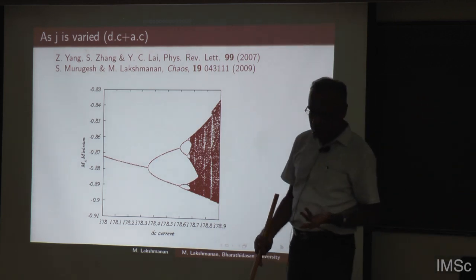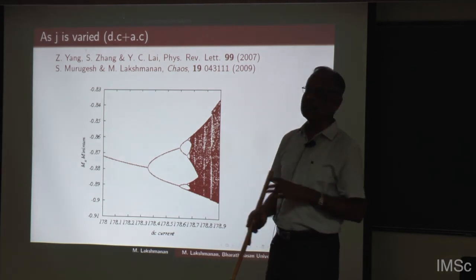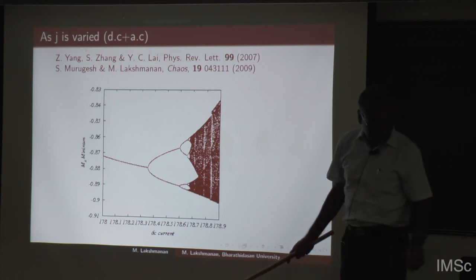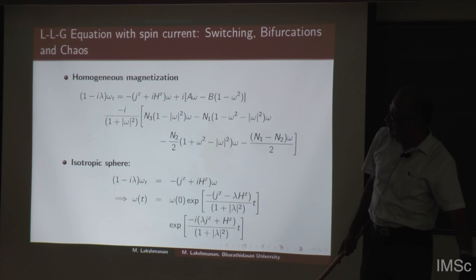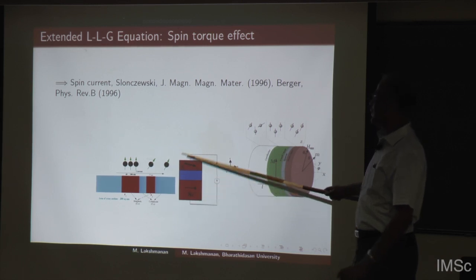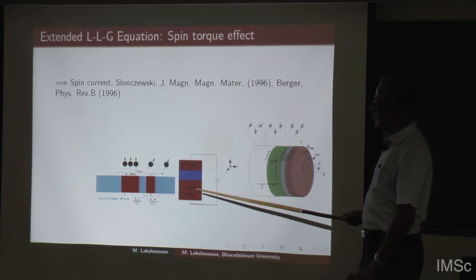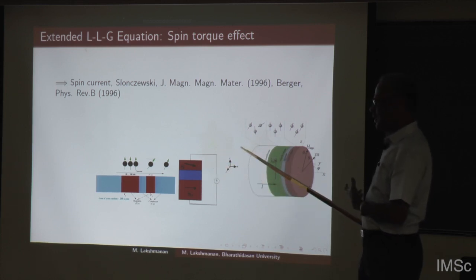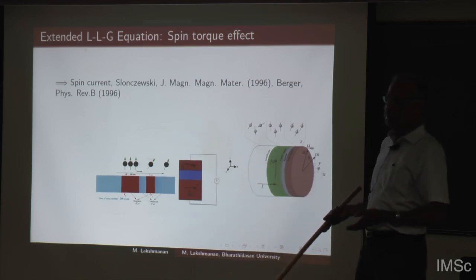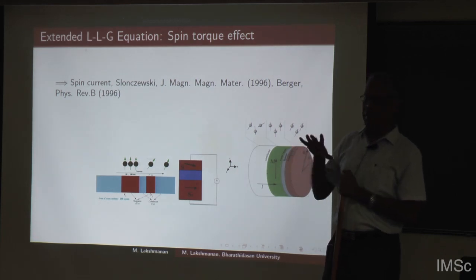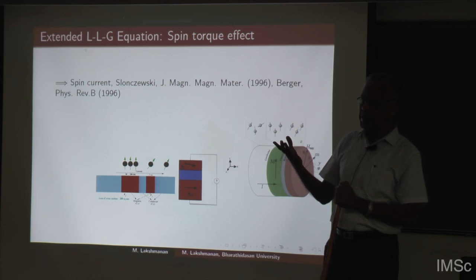But I said that one of the negative aspects of this STNO is its extremely low power. How to enhance this power? For that, I will try to keep many such oscillators. So this is one typical circuit. I can keep many such nano devices, and then connect them serially or in parallel or in a hybrid sense. There are many other possibilities. Couple them appropriately. And then I can also show that under appropriate coupling conditions, the power can be enhanced, of the order of N squared.